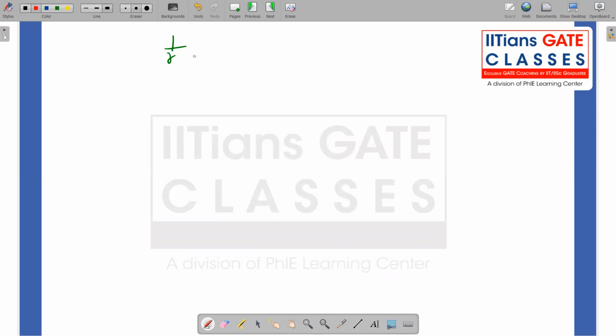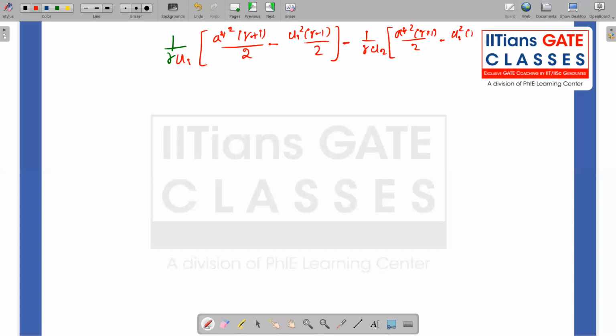So now what I'm having is, let me write it. 1 by gamma u1 times a1 square, where I replace a1 square in terms of a star square times gamma plus 1 divided by 2 minus u1 square times gamma minus 1 divided by 2. Similarly, I have 1 by gamma u2 times a star square times gamma plus 1 divided by 2 minus u2 square times gamma minus 1 divided by 2, which is equal to the right hand side, that is u2 minus u1.